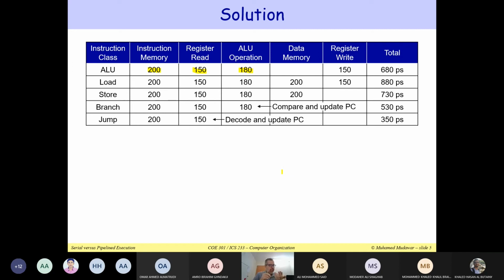So for example, if addition and subtraction take longer than the logic operations, then we focus on the longest delay. Even for addition and subtraction, we have to look at the fact that the sum bits are produced at different delays. We have 32 bits in my result, but the most significant bit will take longer to produce than the least significant bit.